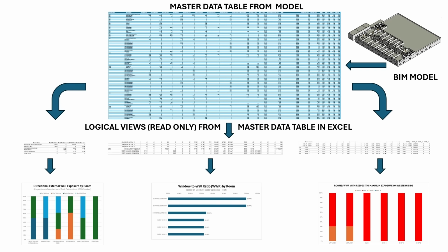Closing concept. So in this episode, we have not performed energy simulation. Instead, we have structured envelope intelligence. We looked at internal heat zoning, solar control properties, external exposure, and glazing intensity. Because meaningful energy strategy begins with understanding the envelope, not with jumping directly to HVAC sizing.